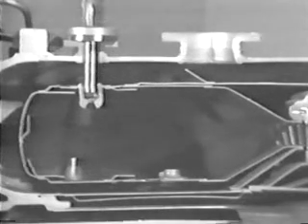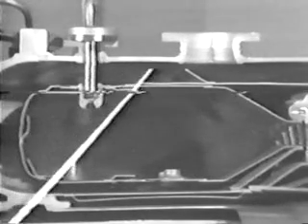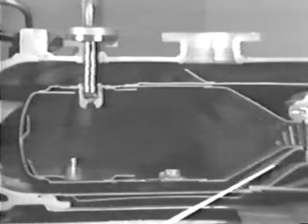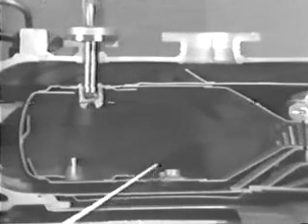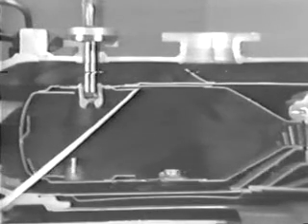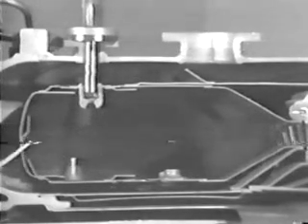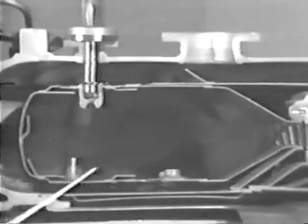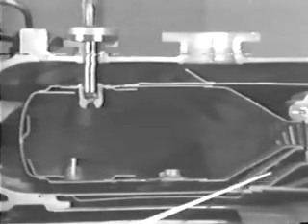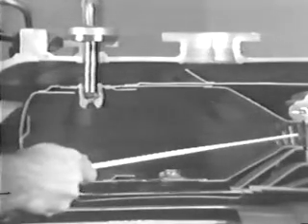To see how these steps occur, let's look at the combustor. It's constructed like two concentric pipes. Combustion occurs between these inner and outer liners. One end of the combustor, the forward end, is covered, forming the dome, while the other end, the aft end, has shrouds which direct hot gases toward the turbine. Combustion takes place near the forward end.